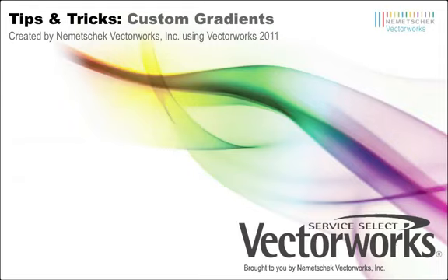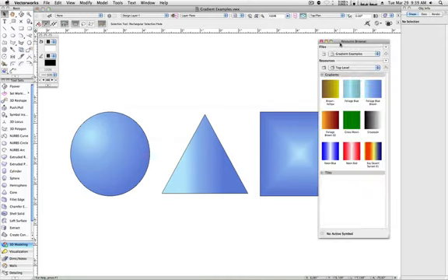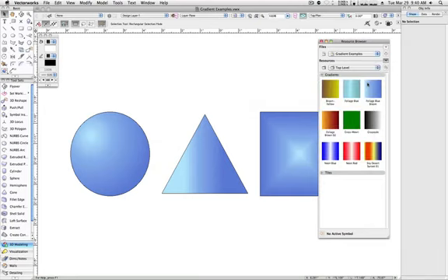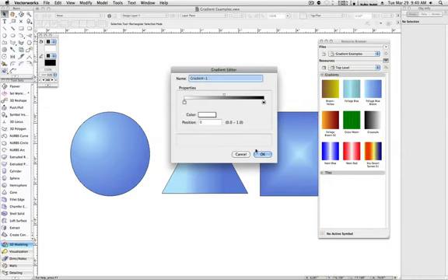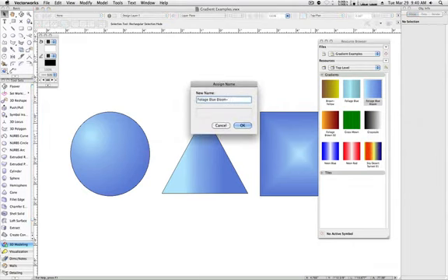Gradients can be used to create visually appealing 2D graphics, as well as mark out areas of different terrain and plant objects. To create or modify a gradient, we go to the resource browser for the current active document. We can either click Resources, New Resource, and choose Gradient, or we can right-click or control-click on an existing gradient to make changes. As with symbols, if we want to keep the original, we can duplicate it, then modify the new duplicate instead.